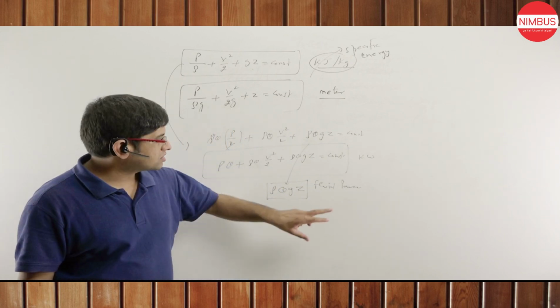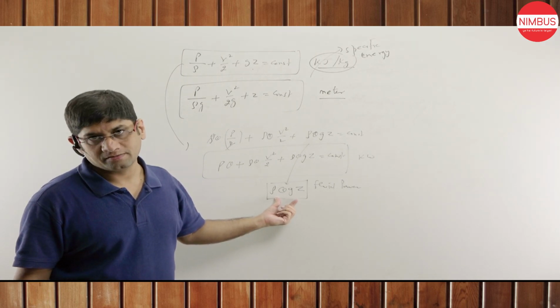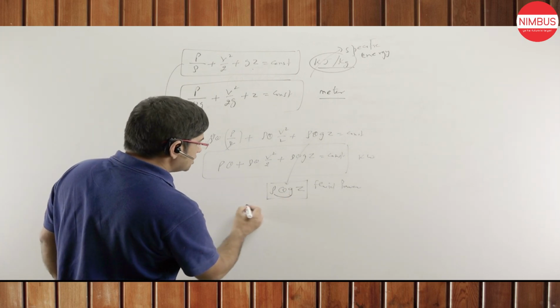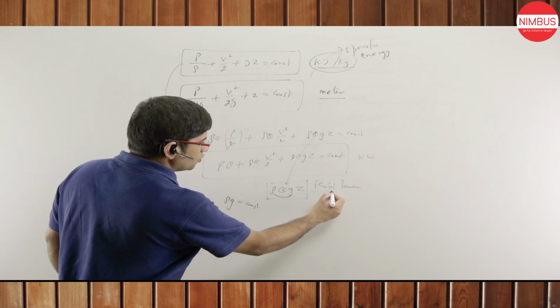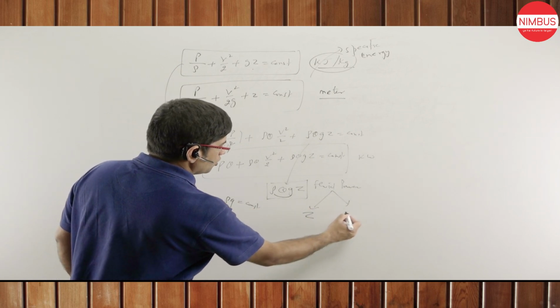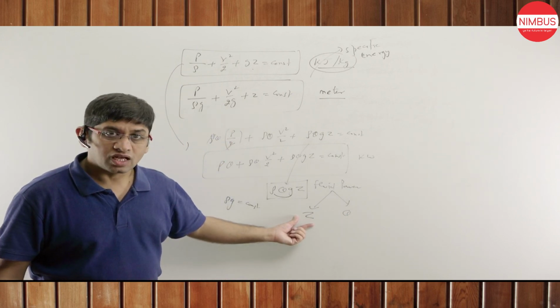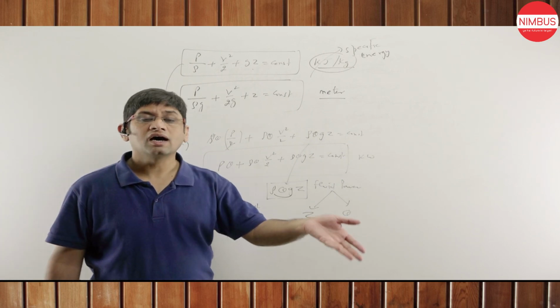Now, on the basis of what power is there inside the fluid, you will use some turbine. Now in this particular formula, rho into G is basically a fluid property, that is constant. That means fluid power either depends upon Z or depends upon the Q. Either the fluid will have more head. If Z is more, use the Pelton turbine. If discharge is more, use the Kaplan turbine.